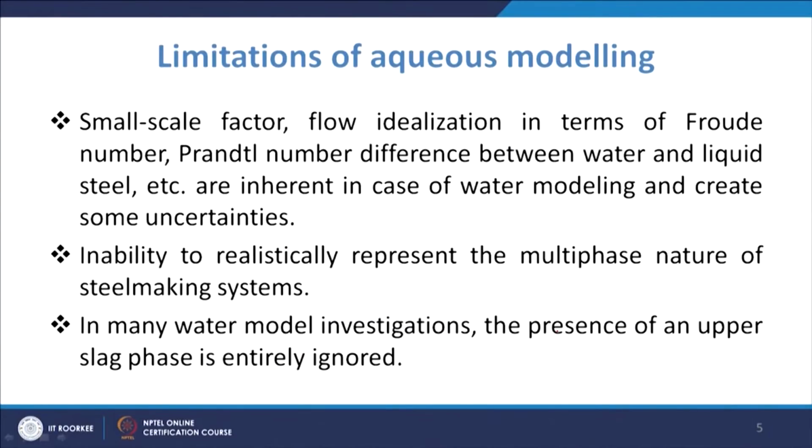Small scale factor, flow idealization in terms of Froude number, Prandtl number difference between water and liquid steel etc. are inherent in case of water modeling, and create the uncertainties, because if you look at the physical properties of water and the steel, you will have the differences in these number values, and they are going to inherently cause certain kind of uncertainties in the case of aqueous modeling, when we are taking water as the working fluid.